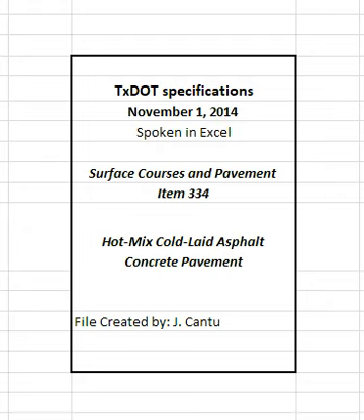4.6 Production testing and operational tolerances. The aggregate gradation and the asphalt binder content of the produced mixture must not vary from the JMF by more than the percentage point tolerances shown in Table 6. The gradation of the produced mixture may fall outside the master grading limits for any of the sieve sizes from the 1.5 inches through the number 50 sieve if it is within the JMF tolerances.